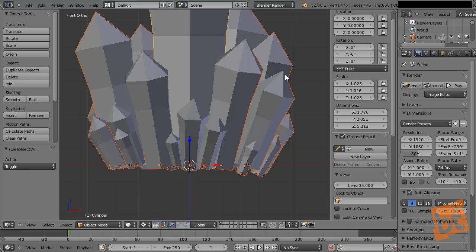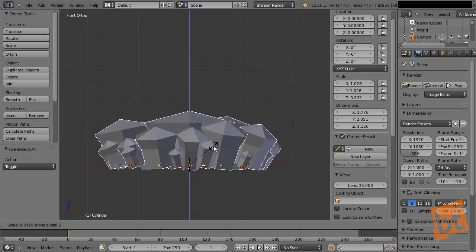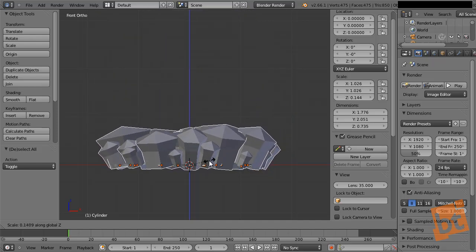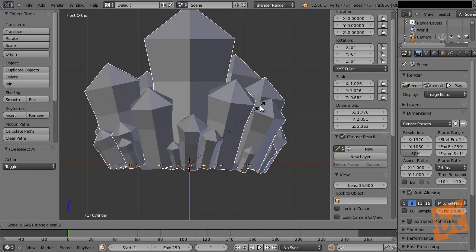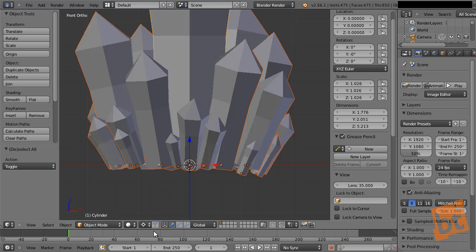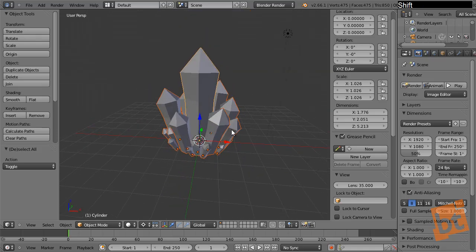And now, if I press S and Z, you can see that we scale everything on Z, and while the objects go closer to the floor, I'm also deforming all the mesh, and I don't want that. So what I want is to activate this option here, which is manipulate center points. All right, so if we activate this, we are only going to affect the center of the object, right? We'll move the object, but the object itself won't be deformed.